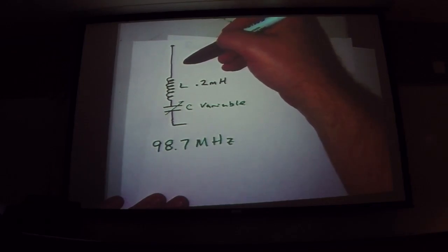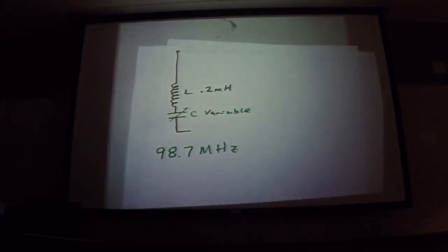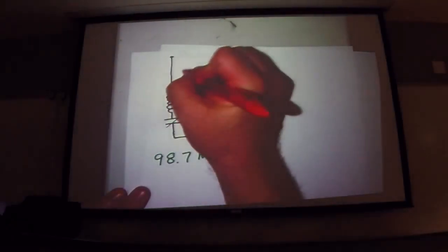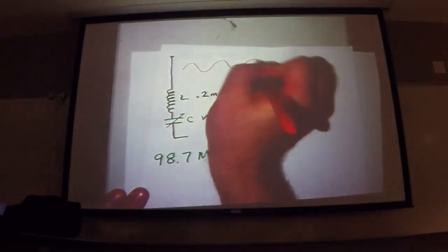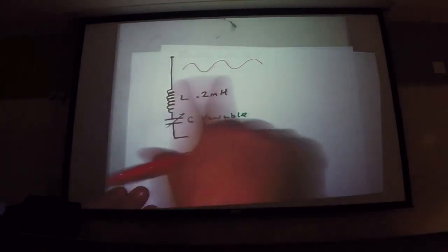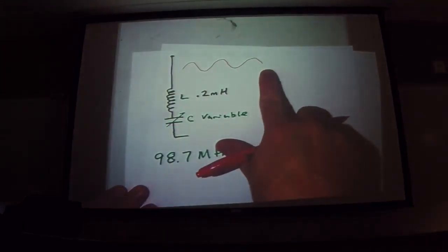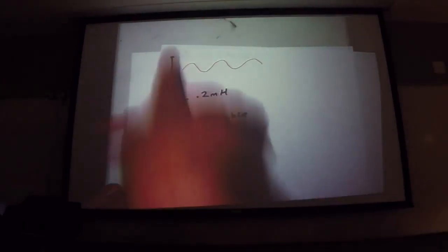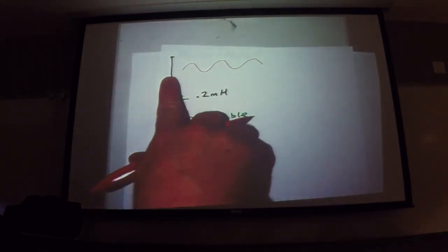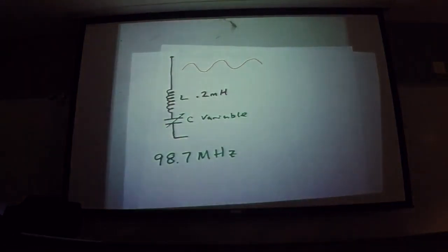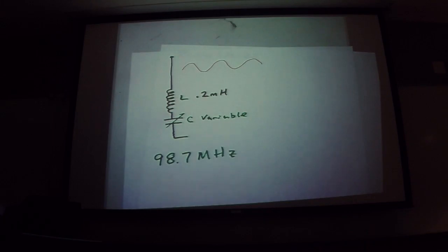Cool, huh? So in other words, the electric field comes along, waving along with the magnetic field. So here's the electric field. The rod antenna is going to couple to the electric field of the electromagnetic wave, and this is going to start pushing. That's why antennas are made out of metal, so they've got electrons in them. It's going to start pushing those electrons up and down with a particular frequency.